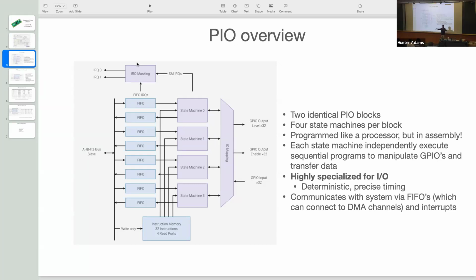It has this tremendously high-speed digital interface, 30 GPIO inputs, and those need to be toggled to 5 nanosecond precision, right? So we're driving this thing at 200 megahertz. They were driving it, of course, with an FPGA. Over the course of about a year, we were able to replace that FPGA with an RP2040. The FPGA cost $500. This cost $1. Right? It's really interesting in that it makes this little $1 microcontroller a reasonable substitute for a device for some applications where really the only other reasonable device for a long time was something much, much, much more expensive.